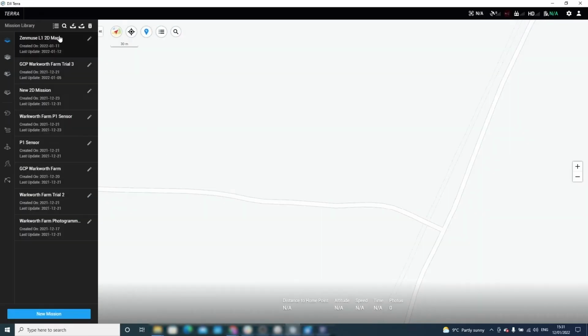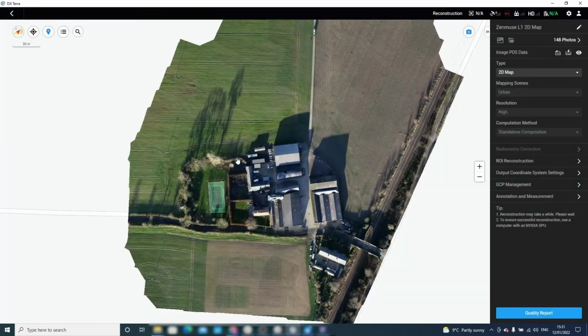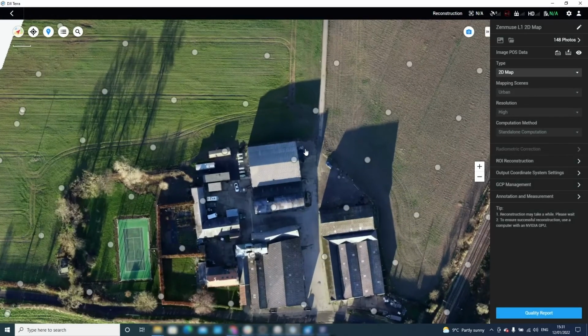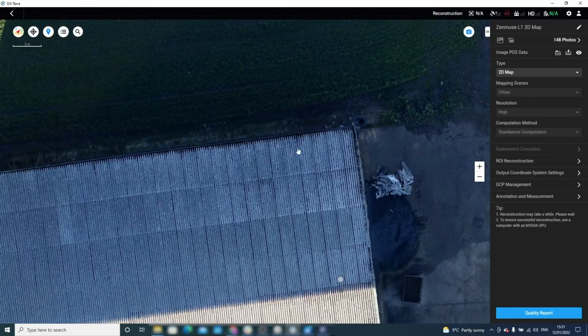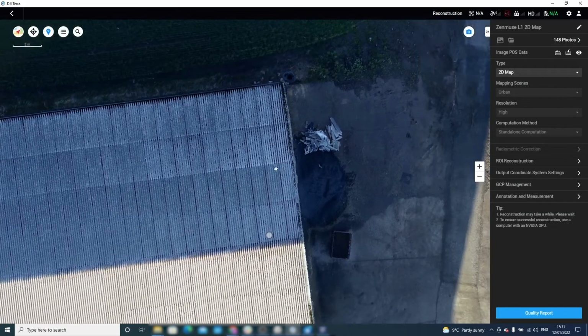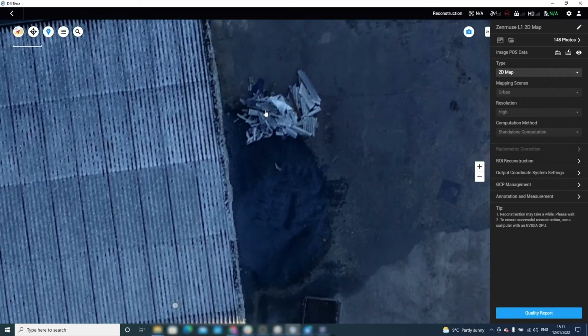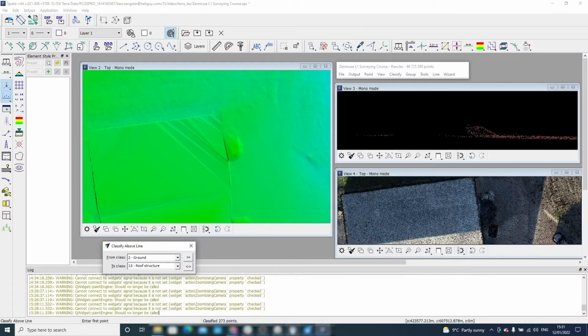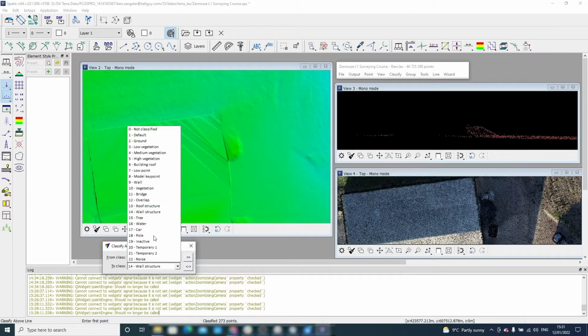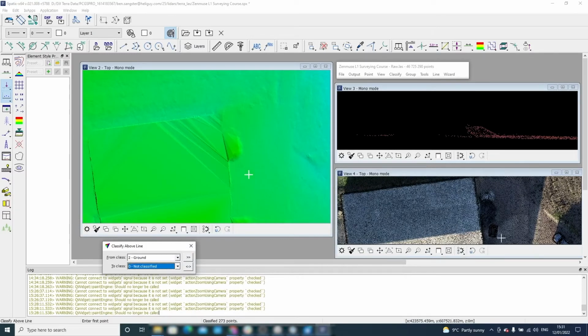However, there is another part just off the building roof that I am unable to verify from the RGB point cloud. So using the DJI Terra 2D ortho photo, I'm going to zoom into this section of the image to work out what this land feature is. Looking at this feature now, it looks like an area of debris just off the farmhouse. I can't find a point class for loose debris, so I'm just going to set this bit of data as unclassified.